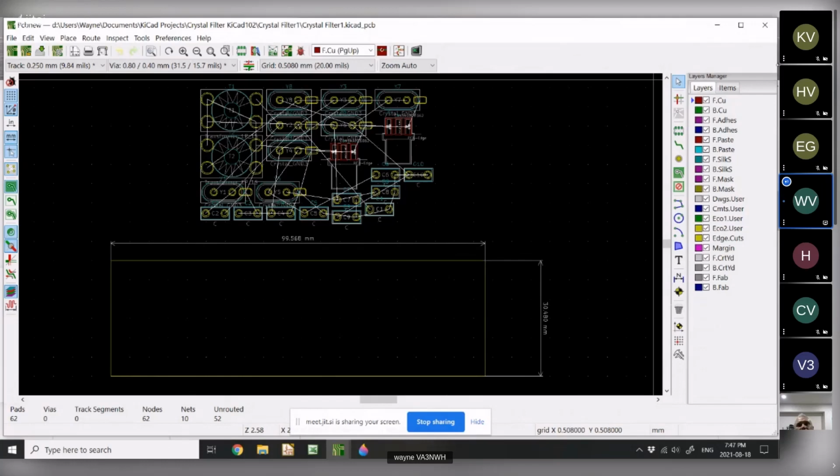You have to go over to the layers. So let me talk about the layers first. Here's your 2 copper layers. These 2 layers, I have no clue what they are. Paste is for making a paste template, I believe, for SMD. Silk is a silk screen layer. That's where the writing goes. You notice they're in pairs because it's got front and back. If I had selected multiple layers, I'd have more than 2, all right?